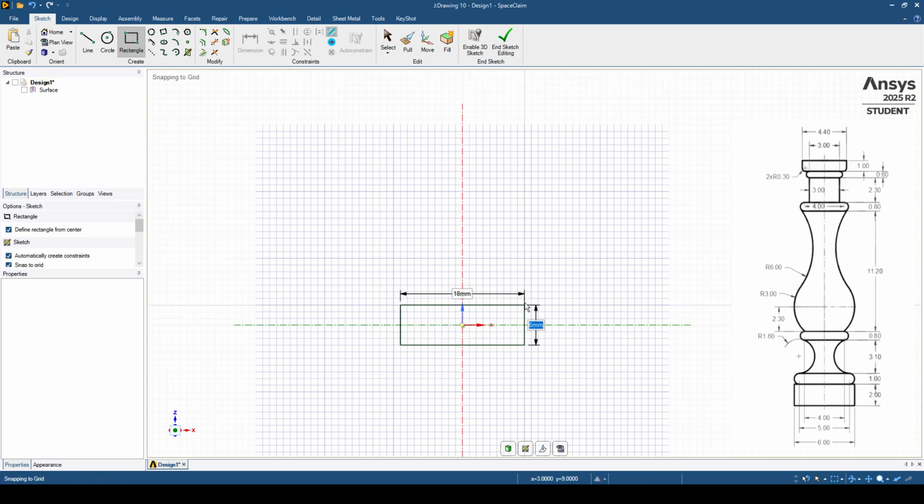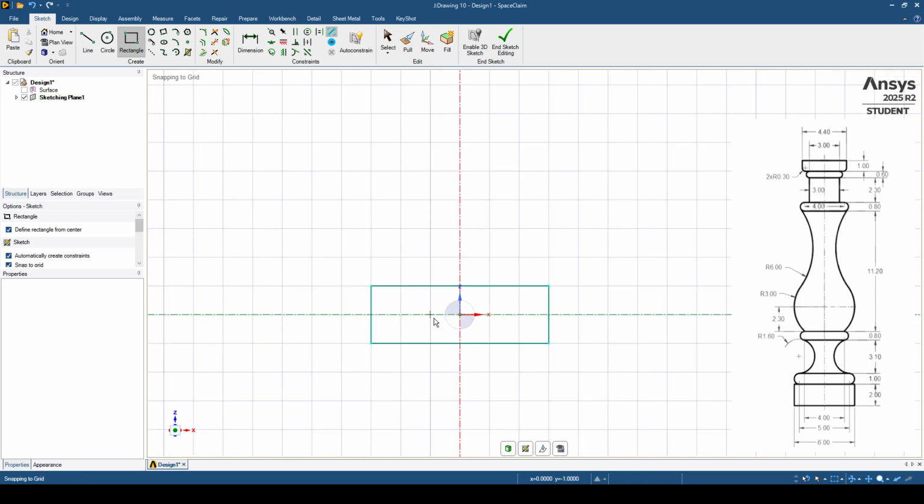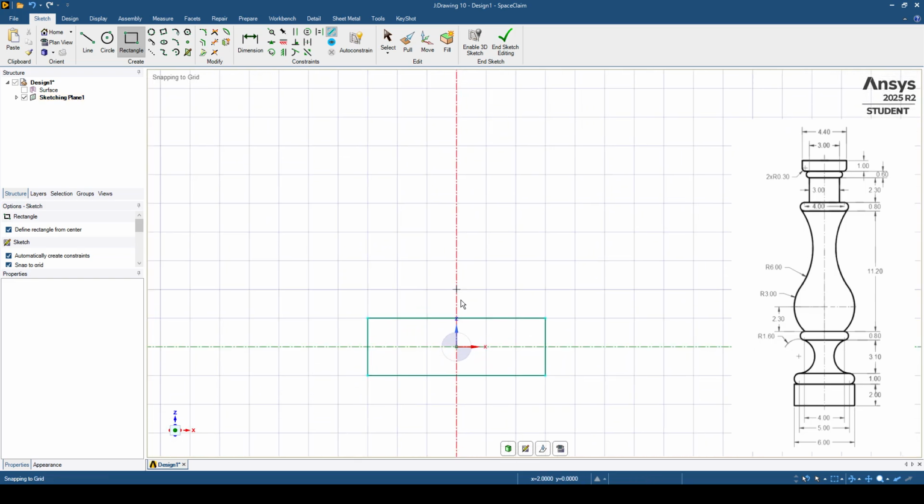So the rectangle on the bottom has a height of 2 millimeter. Then I hit tab. After that, it's with a 6 millimeter width, and enter. So now we have this bottom rectangular form. Let's draw the small one above, and in order to do this I'm also going to use, as in the whole video, the rectangle from the center.